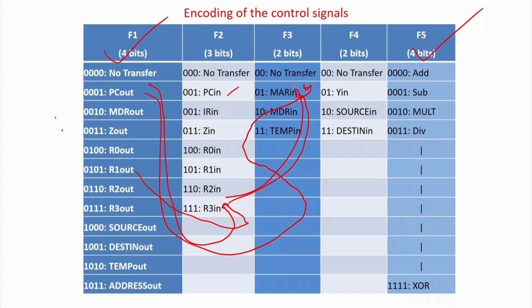So in that philosophy, they have decided to put the user registers over here and the memory address register or the memory data register or temp in another cluster. That means simultaneously one register can be made 1 here, and one register can be made 1 here, and even one register can be made 1 here, the input. So simultaneously some output can be fed to one register over here, one register over here and one register over here. That is where simultaneous input is possible, and that way you divide the cluster.